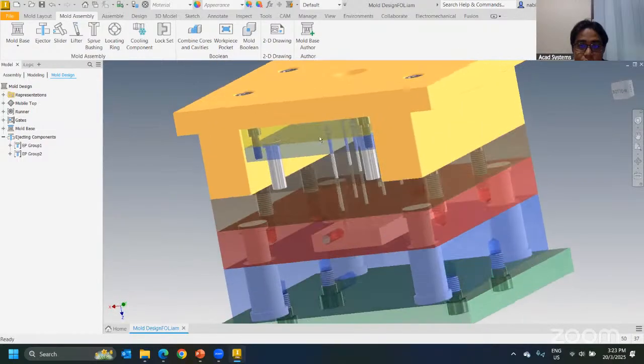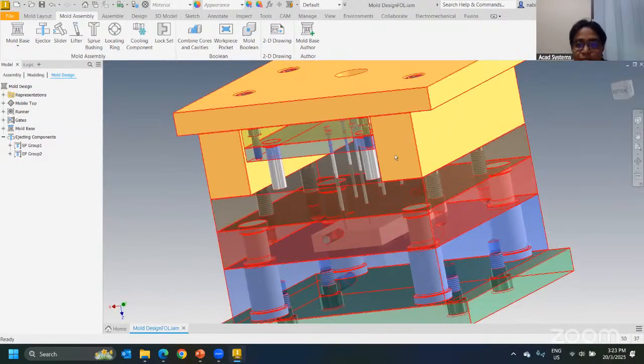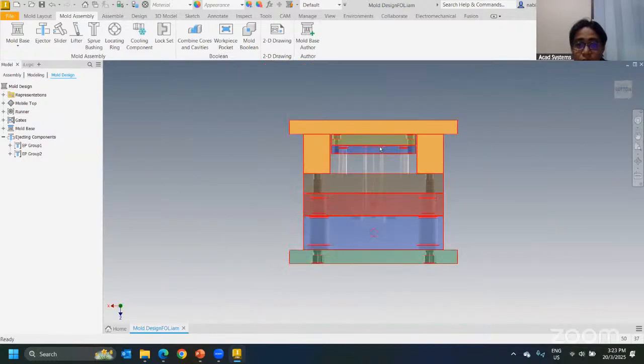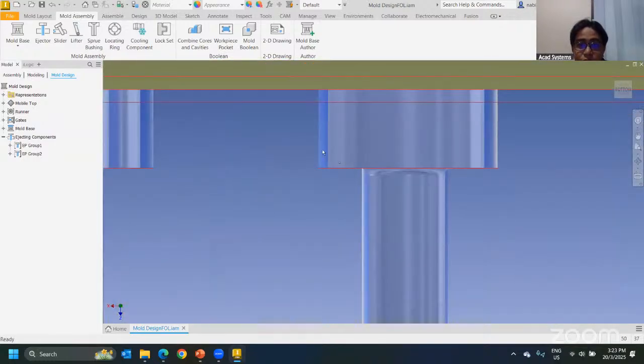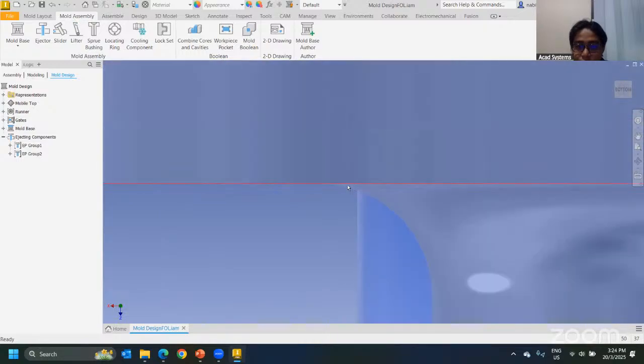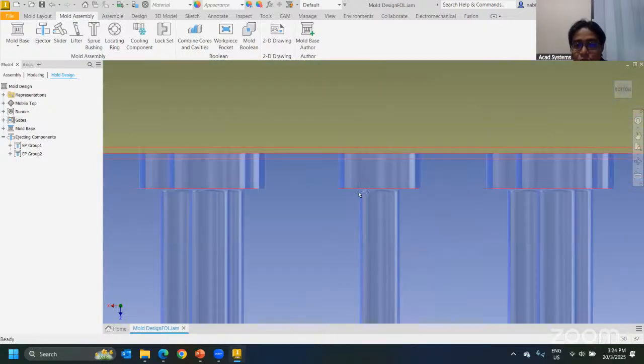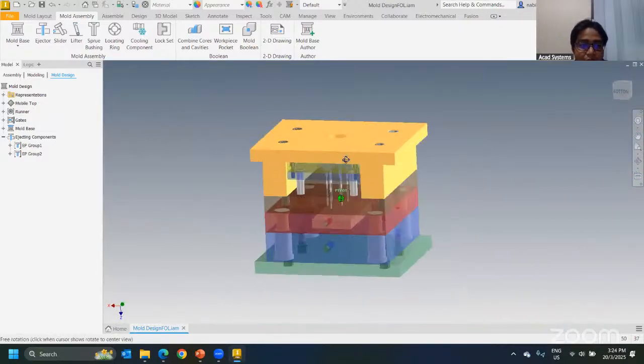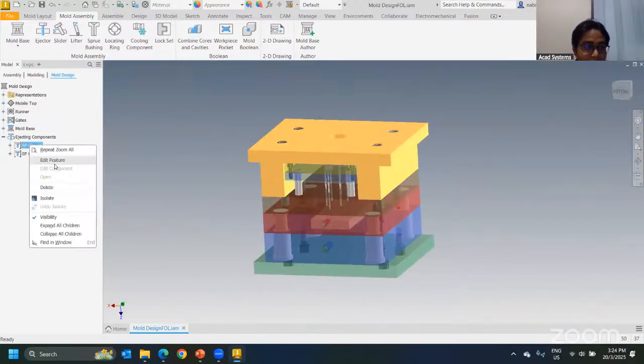And if you see here, there is a pop-out message indicating that there is a clearance issue. So if I go and zoom in inside, then you should be able to see that we actually have a clearance area inside here. And in this case, it's already penetrating. So I needed to adjust the clearance. For the clearance, you can just go back and edit again.